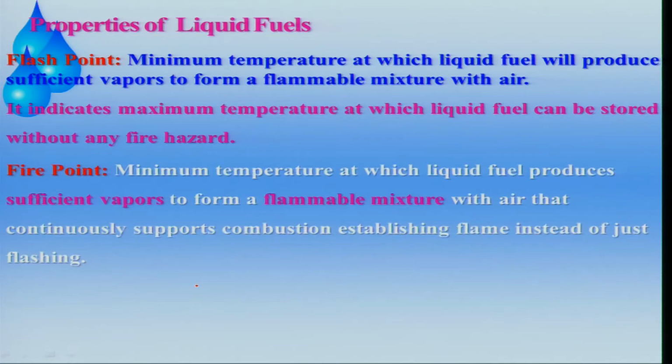The fire point indicates the minimum temperature at which a liquid fuel produces sufficient vapor to form a flammable mixture with air, right, that continuously supports combustion, establishing a flame instead of just flashing. That means it will ensure a continuous combustion, right. So, when I am talking about sustaining combustion, I should go beyond the fire point, right. And when I am talking about storage, the temperature at which I store a fuel must be less than the flash point.